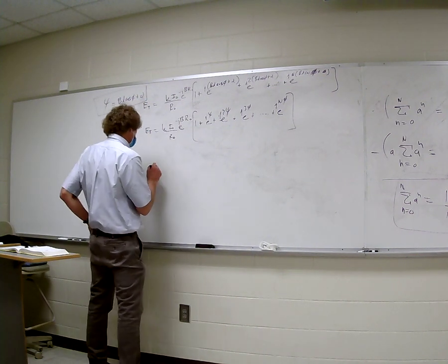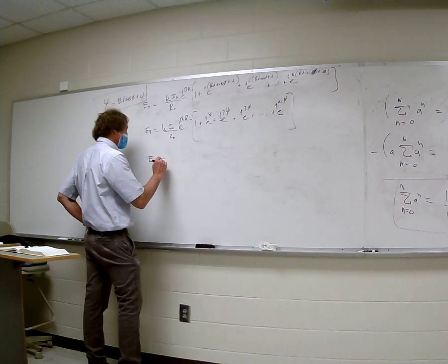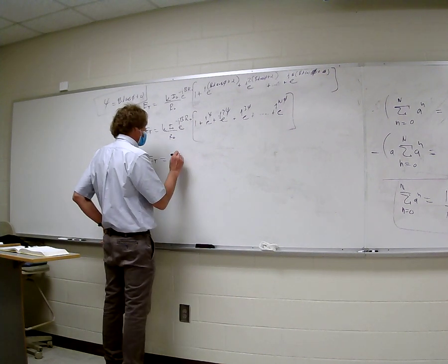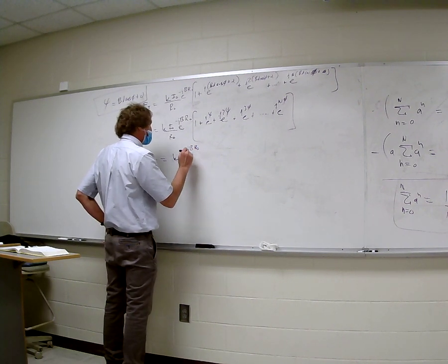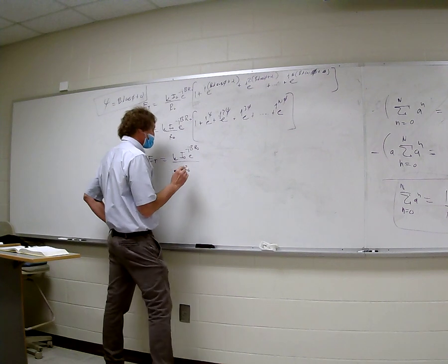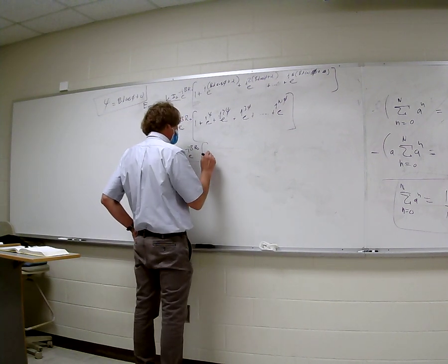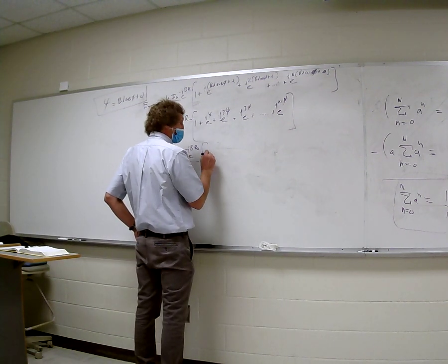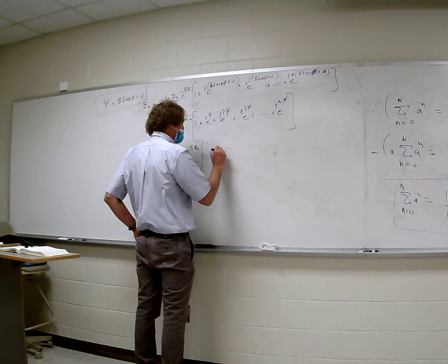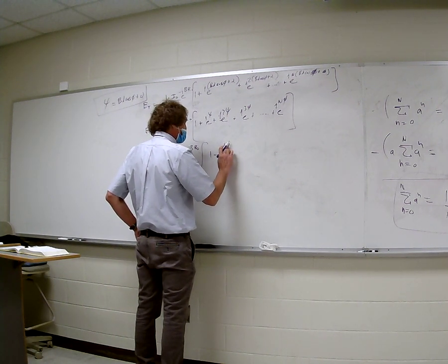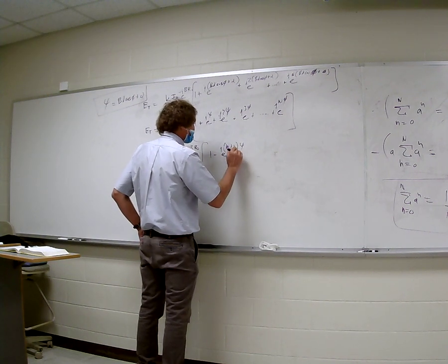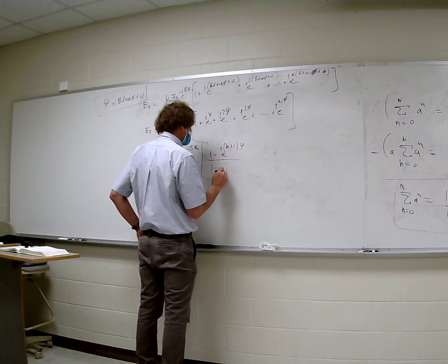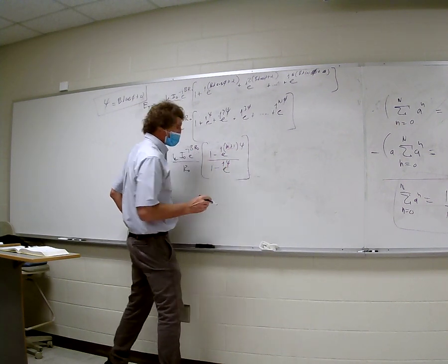In other words, this whole series, I'm going to get to this, is equal to k I naught e to the minus j beta r naught over r naught. Now this is an isotropic series. Then it's going to be times 1 minus e to the j(n+1)psi over 1 minus e to the j psi. Agreed?